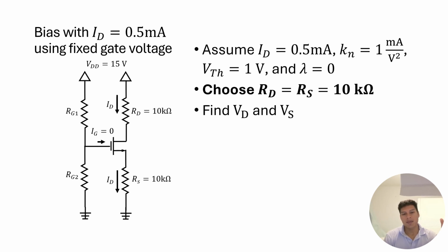What you will see when we look at the amplifier analysis is that we will actually use the same 4 resistor topology to bias our MOS amplifiers, and it will be kind of the building block that we will use for amplifiers. So it's basically the circuit that you really need to know how to analyze.